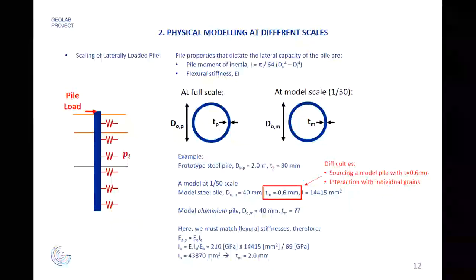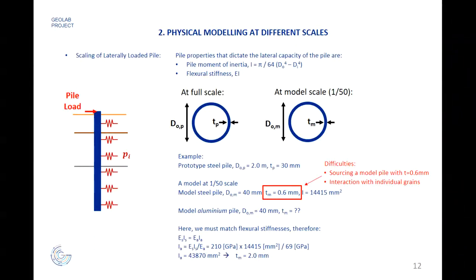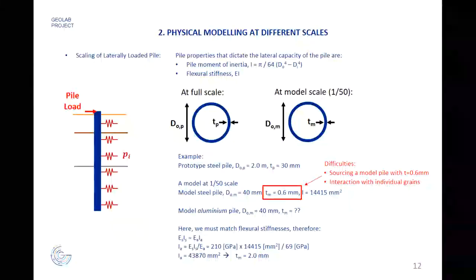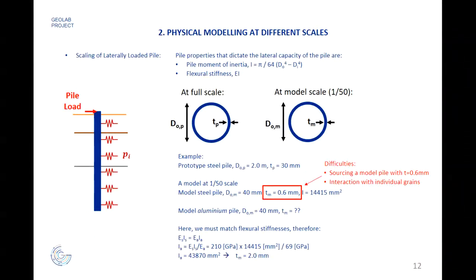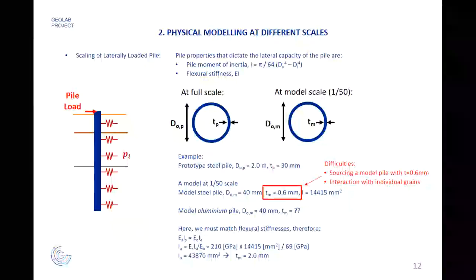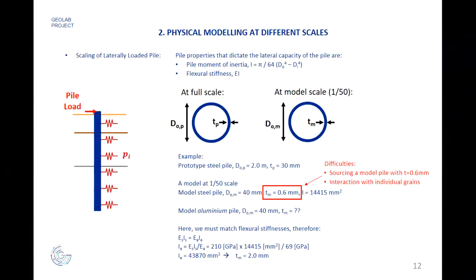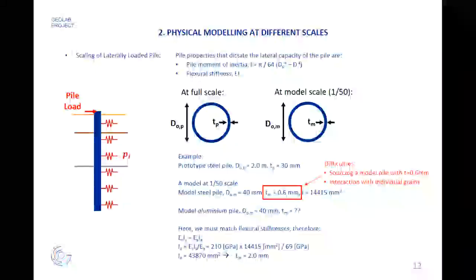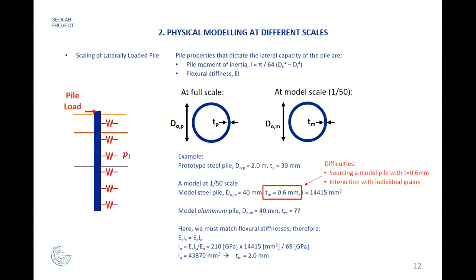Concerning the pile behavior under lateral load, the main parameter is the flexural rigidity, the product of E and I. E is the Young modulus, and I is the second moment of area, to be accurate, the inertia.